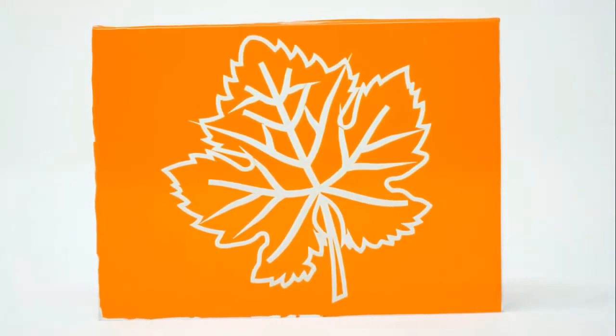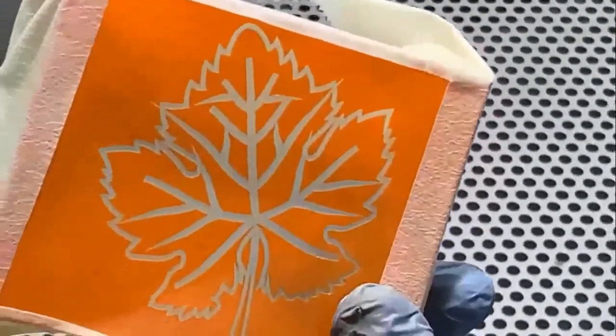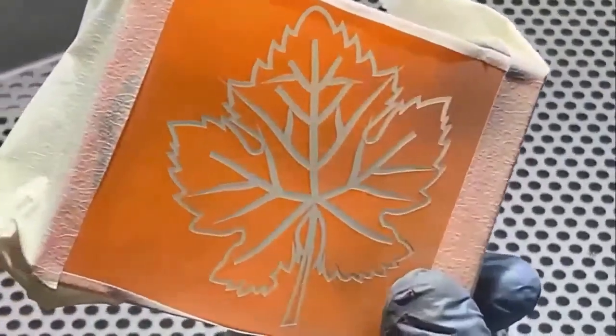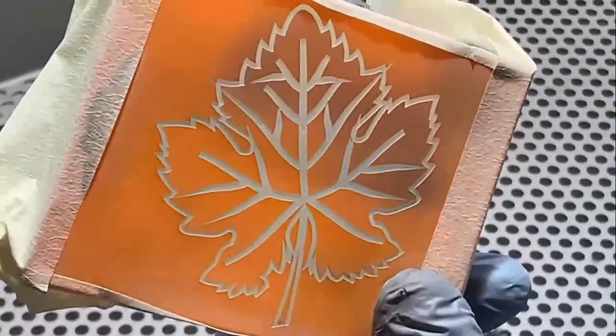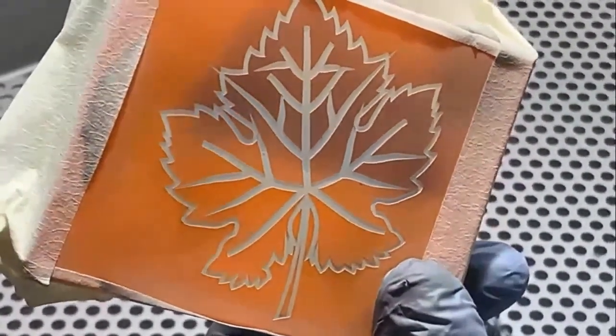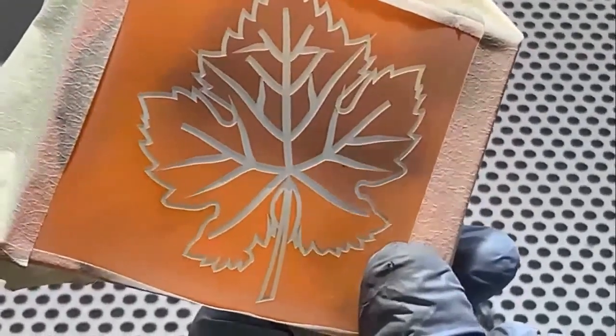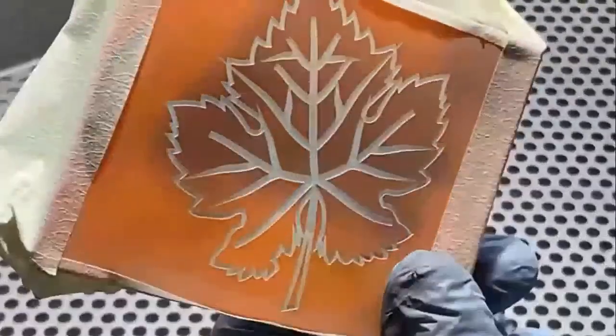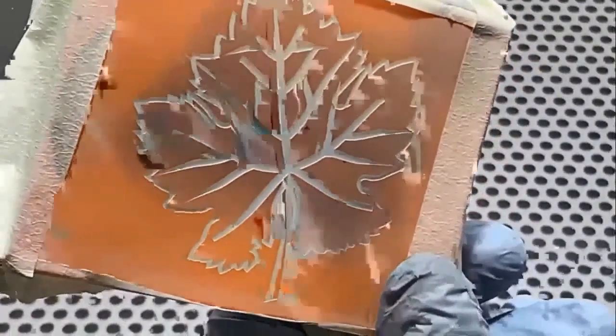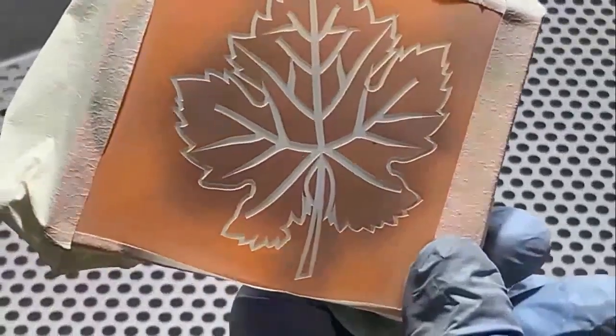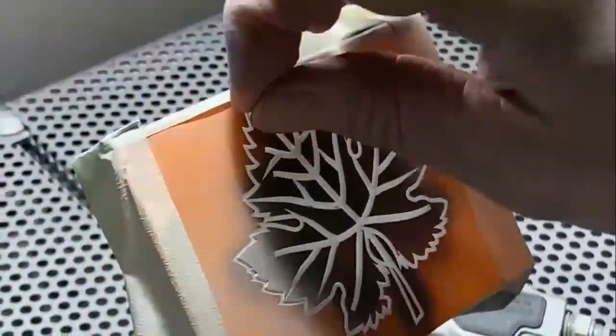So the fish image is popular, but another main image that our customers like to play with is our maple leaf. This one here, we're going to do a 2-stage. So what we're doing again is removing the membrane, which is very easily removed with the abrasive. We are blasting under 30 psi with a pressure pot system, and just doing a little run through to remove that membrane so that we have islands.